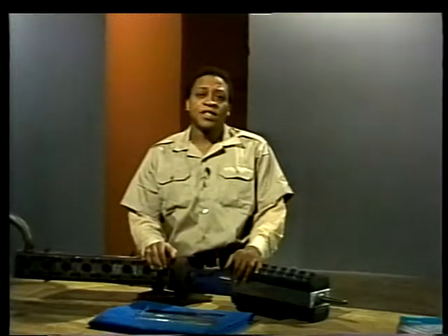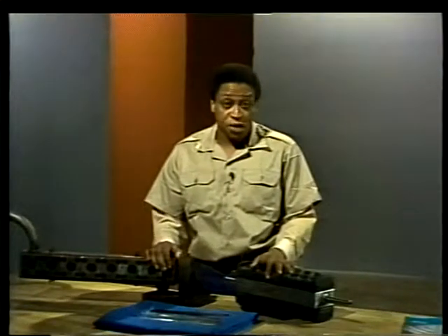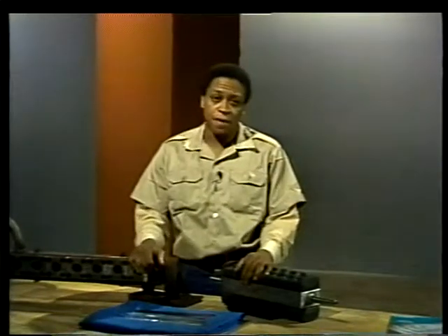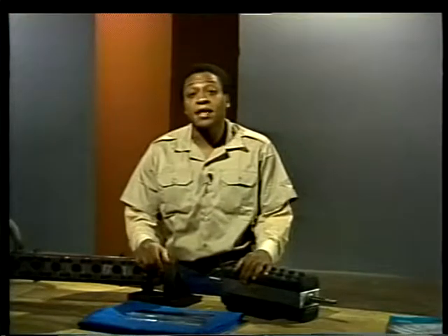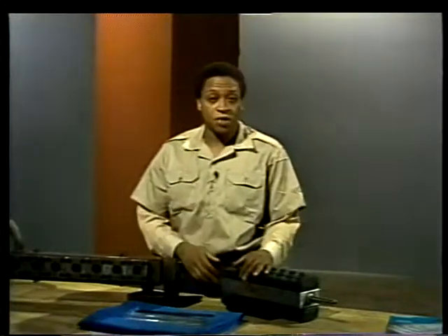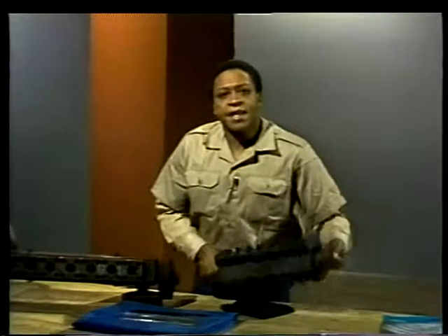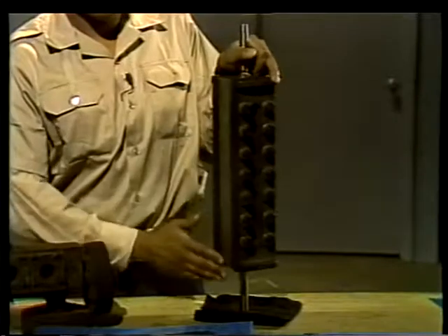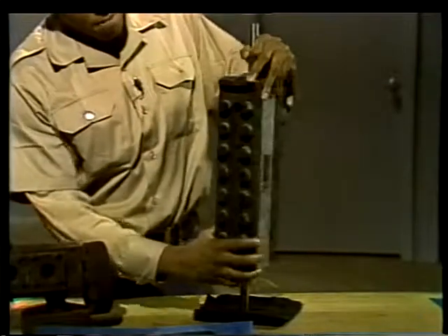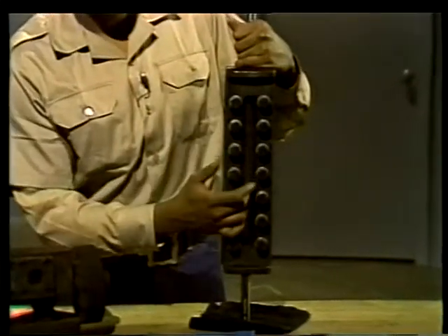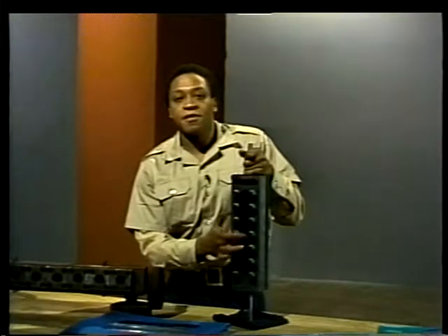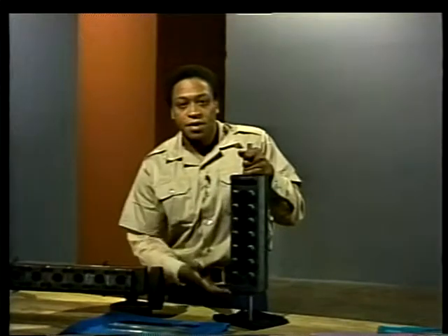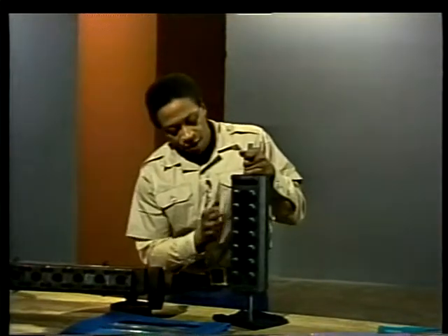The second kind of gauge glass, the flat glass type, is stronger, more rugged, and more suitable for use at higher pressures than the tubular type. So it is often used to indicate levels in steam drums and feed water heaters. A typical flat glass gauge, like this one, has a metal body that is open on both sides. Each side is covered with a thick piece of flat glass held in place by a cover plate. That cover plate is bolted to the gauge.